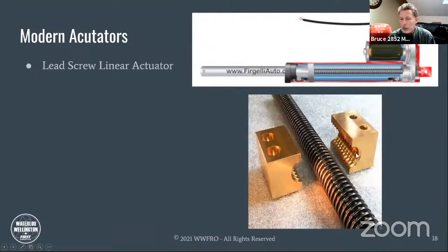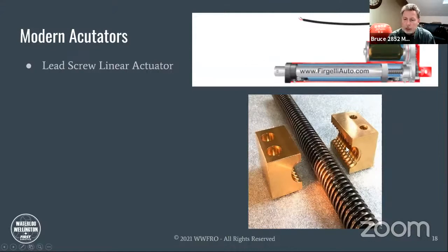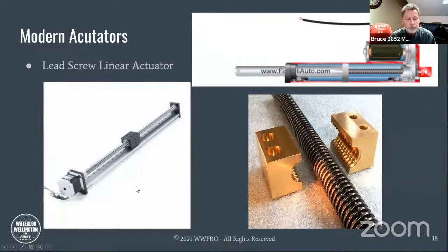This is what it would look like in close-up. Here we have a threaded rod, which looks like it's got a square Acme thread. We see, in this case, a split nut, so it's nice you can see the inside of the thread. It has a mating inside thread for mating with the outside thread of the rod. In assembly, this might look something like this. A motor turning the threaded rod, causing the nut to move back and forth. You would attach something to this plate and you would get some useful motion.